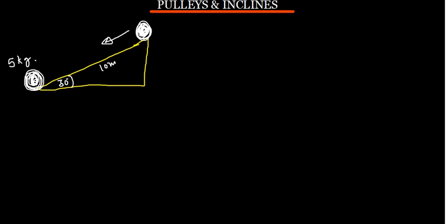So I want now to find the velocity which it is going to have at this position. So on top where it is, it has got, of course, potential energy because it's not moving. So as it gets to go down, the potential energy is going to be converted into kinetic energy because it's moving. Now remember, it's not only moving, it is also rotating, so it is going to have rotational kinetic energy.